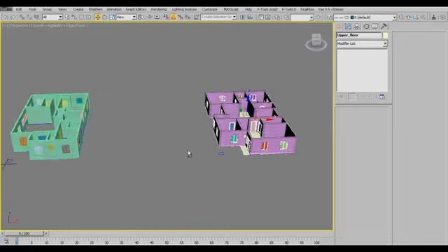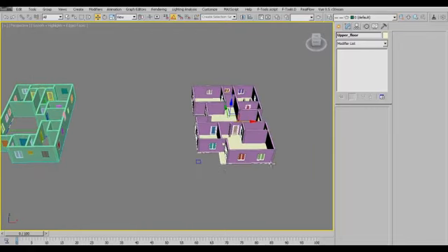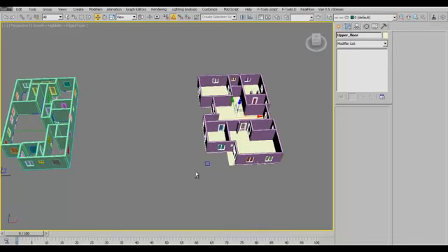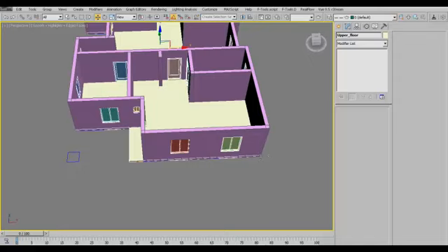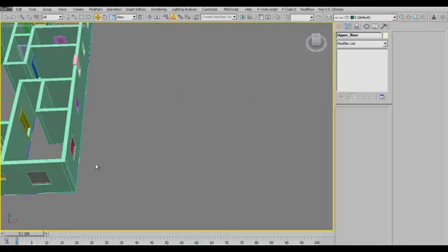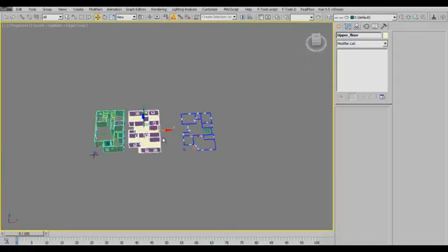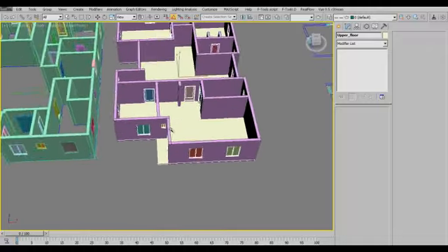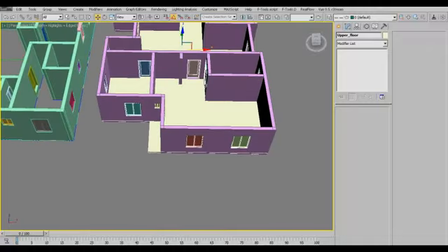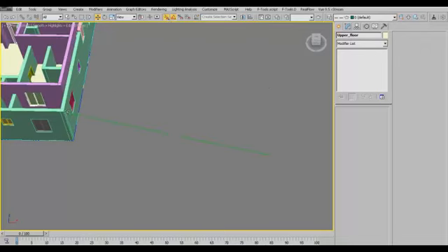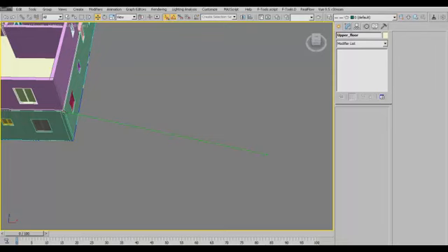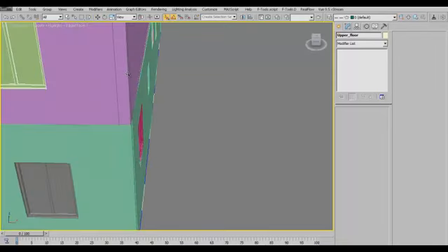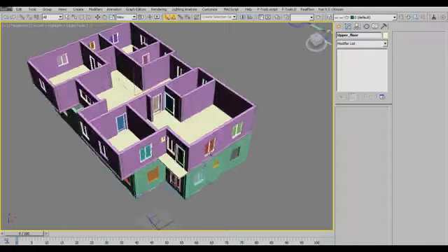Okay, and one thing is now we turn on our snap, so we can actually pick this guy and dump it on top of this, and we'll pick reference point, which is going to be this point and this point. So let's take note of that. Let's move it a little bit closer so we can see where our points will come in. And we turn on our snap now. This time we use a 3-point snap, and once you see that crosshair, then you just place it right here and dump it over there, and voila, we have our walls placed on each other.